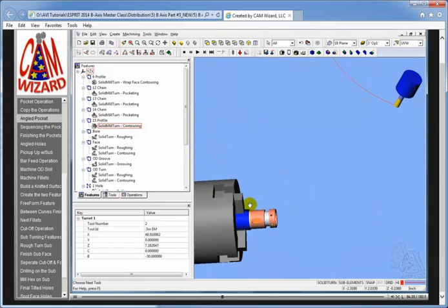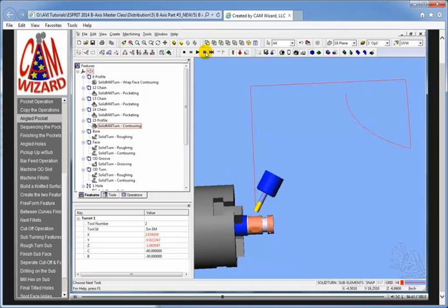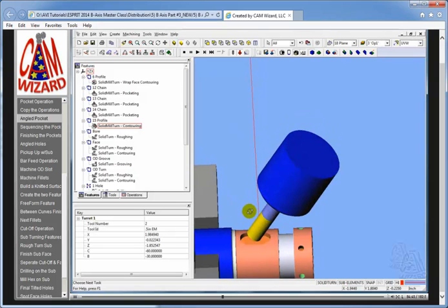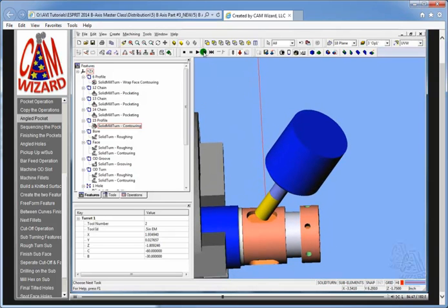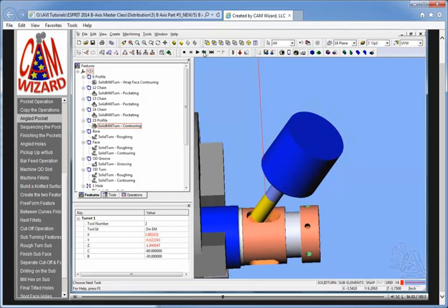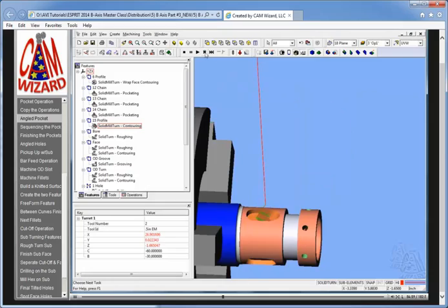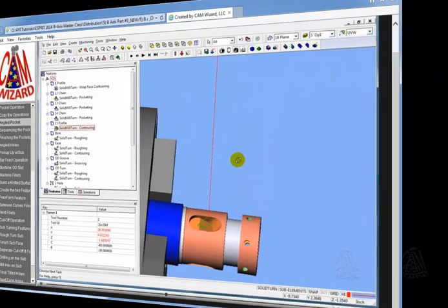Now what's going to happen is that tool is going to index. It indexes to that 30 degrees, which happens to be the angle. Didn't know that till now. Now we know the angle. Now it's going down to the clearance. It's going to go in for the first cut, make a pass, position, feed down to the next level, make the next pass, and then one more pass down the next level to do a cleanup and retract. And now we've milled that area.